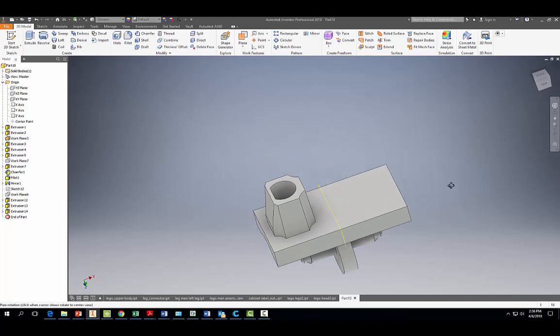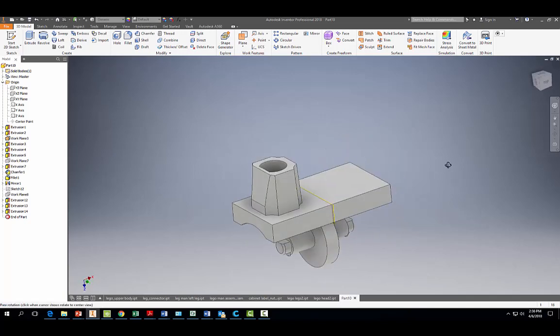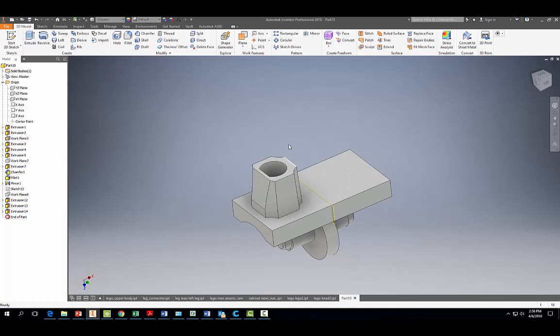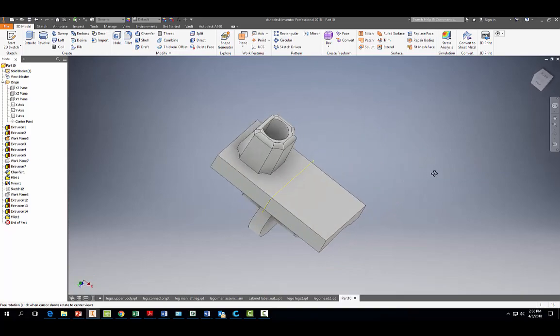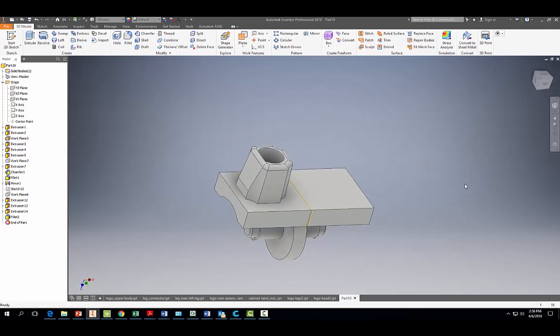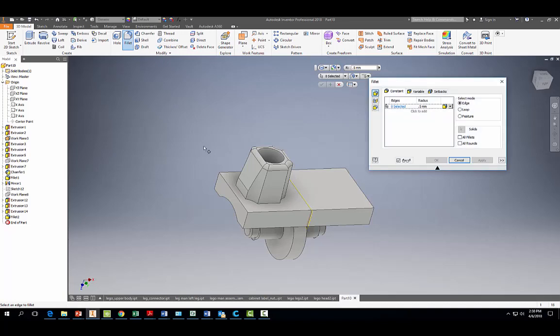And now, if you look carefully at your Lego Man connector piece, it's kind of rounded around the top here. So we're going to throw on some fillets all the way around, and we're going to make those a radius of 0.5. Hit apply and cancel. All right, looking pretty good. We're also going to add a fillet right here of 0.5. I forgot to do that.